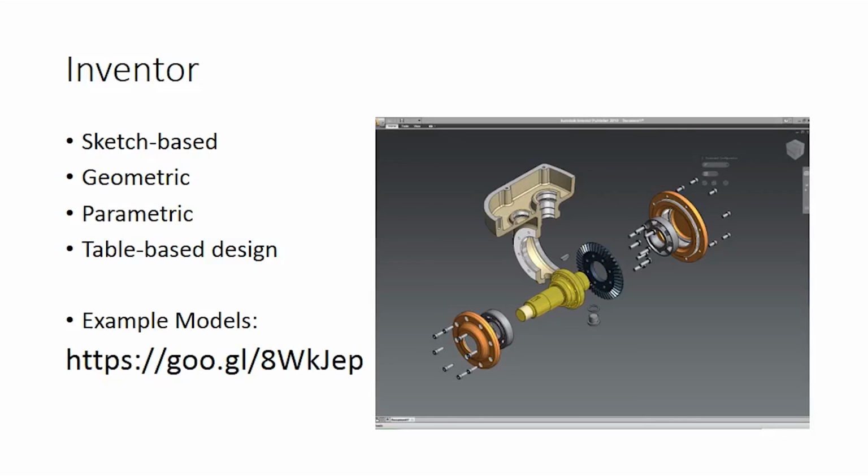So if you have a model that is a generic copy of something, like a bolt, for example, and this bolt has different lengths. Say you have a 3-inch bolt and a 4-inch bolt and a 5-inch bolt. You can design that part to take data from an Excel spreadsheet, and you can add rows to that spreadsheet that will define parameters for this model in different forms, and you can automatically generate all the copies of the model for those different table rows. And that's just one of the many, many features that are built into this program. And I'll address that probably in the next 3D printing workshop, if anybody's interested.